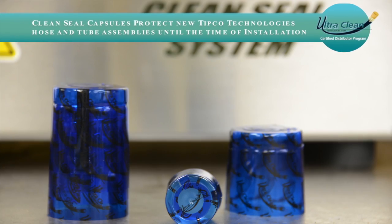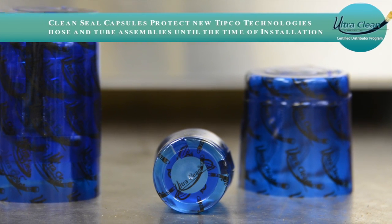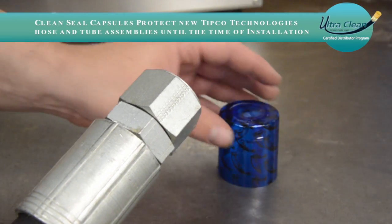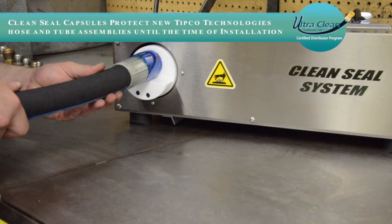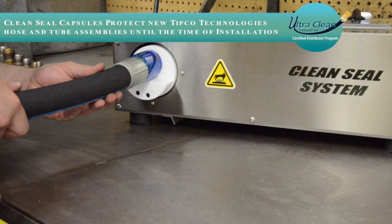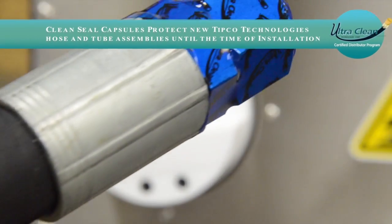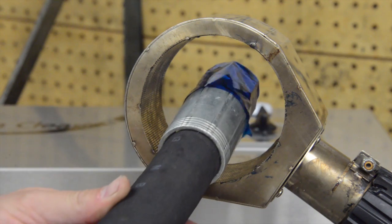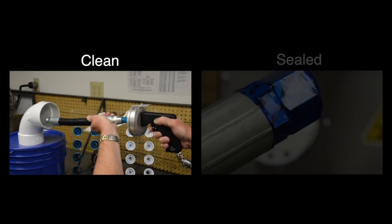You should now use UltraClean's Clean Seal capsules to ensure that the assembly stays clean and contamination-free. Slide the correct size Clean Seal capsule over the end fitting. Place the Clean Seal capsule against the white plunger and push in. If using the UltraClean HL1910E heat gun, move the capped hose end inside of the diffuser. A complete seal takes place in less than 2 seconds. The assembly is now cleaned and protected from contamination.